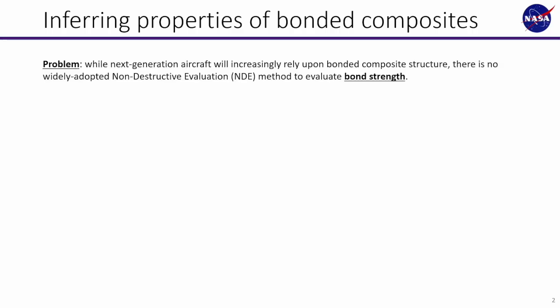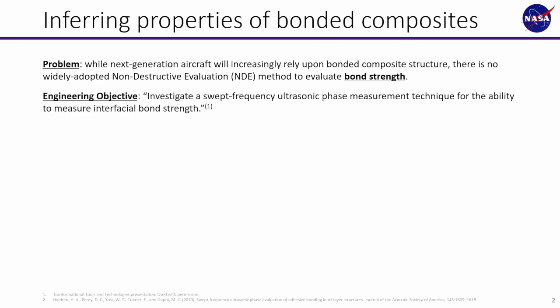from this idea that next generation aircraft will increasingly rely upon bonding composite structure, and there's no widely adopted non-destructive evaluation, or NDE as I'll call it, method to evaluate bond strength. So the engineering objective that we are building upon is to investigate a swept frequency ultrasonic phase measurement technique for the ability to measure interfacial bond strength.